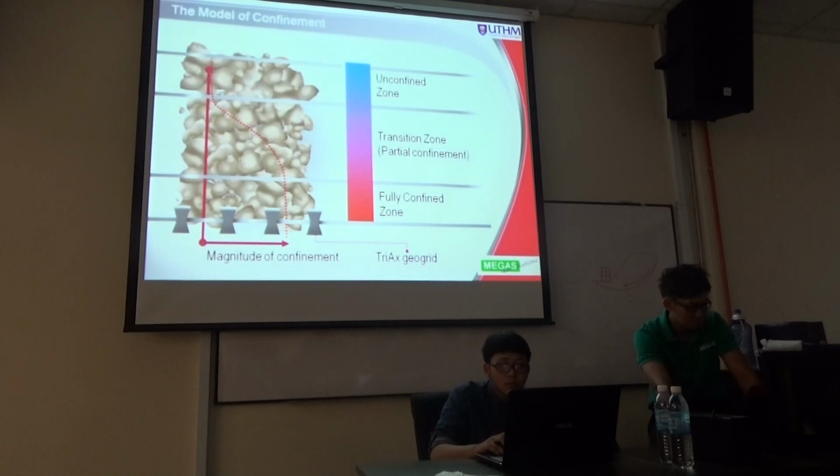In this diagram, there is always an effective confinement zone or interlocking zone for one layer of the grid. We always recommend a minimum of 150 mm to form the interlocking. Too little cannot. Okay? And if it's very thick, more than 400 mm, we recommend another layer of this interlocking geogrid to be placed. So for one layer, the thickness is from 150 mm to 400 mm.